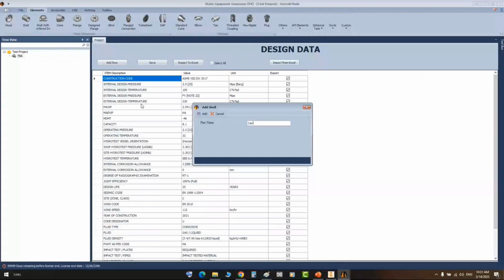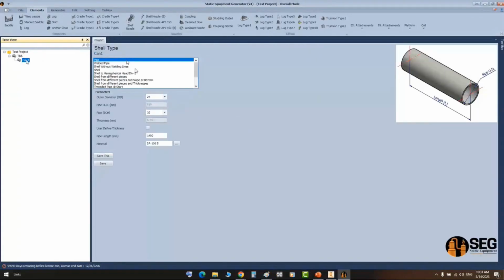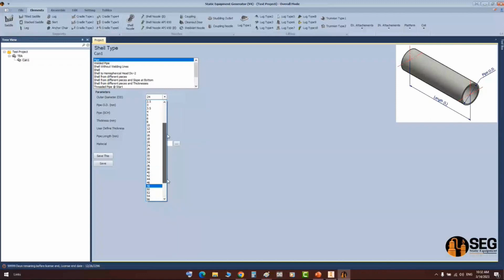Okay. From here, the first type you will meet is a pipe. In that case, you can make this shell as a pipe. You can select the size of this pipe from standard pipe sizes, from 0.125 inches up to 80 inches. So the size you can define from here. After that, you will find the outside diameter in the next text box, and you will find it disabled. You will get the values in this text box. That is the outside diameter of the pipe.